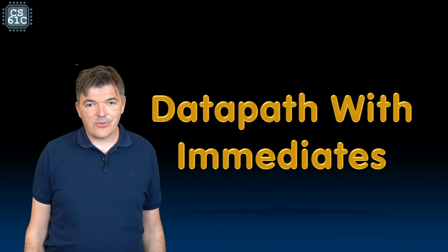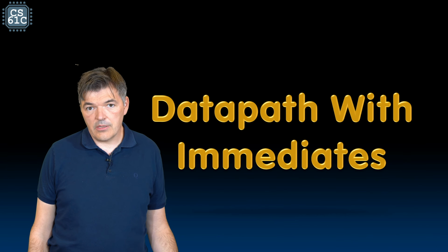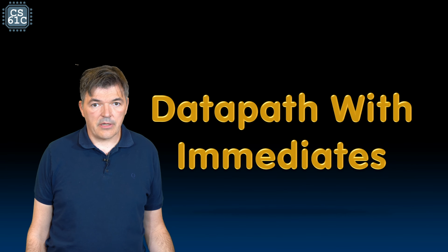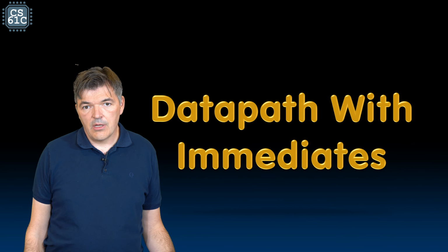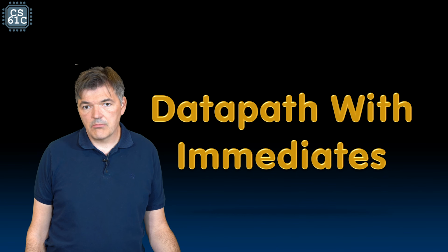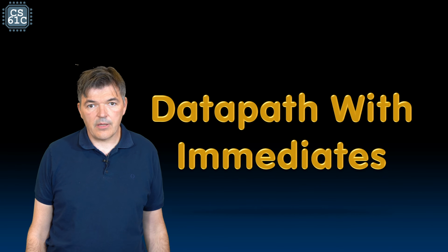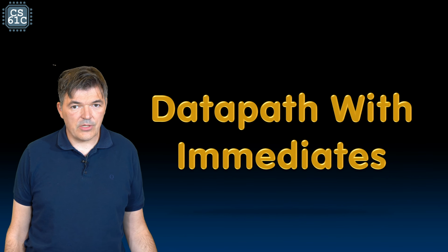Hi, welcome back. Let's continue with our RISC-V CPU design. We have designed a data path and a control that supports all R types. We have seen how we support the execution of the register-based addition and then extended it to support subtraction and then all the other R types. Let's see what we need in order to support operations with immediates.